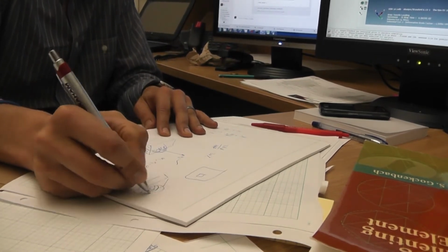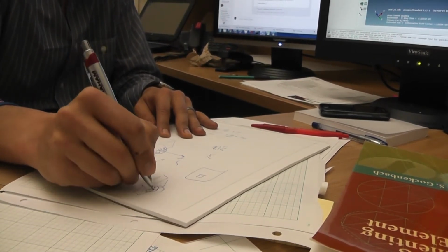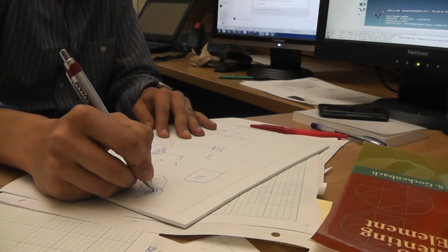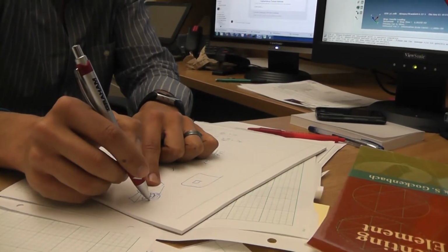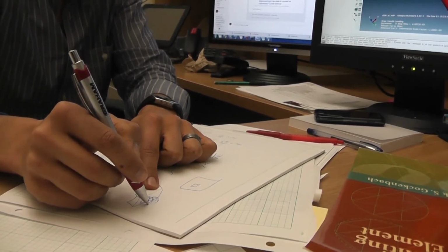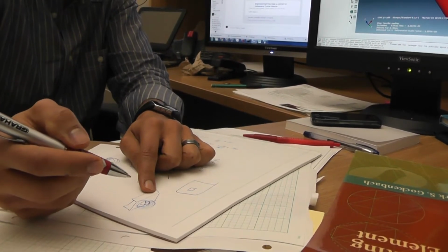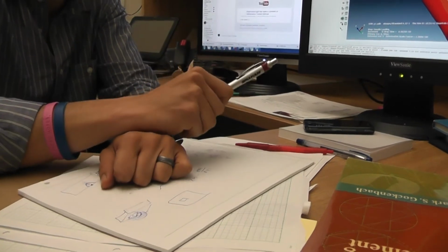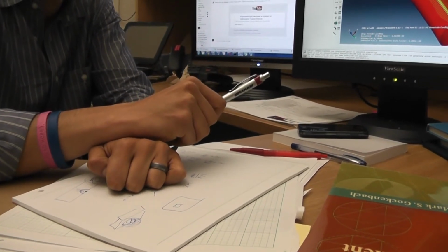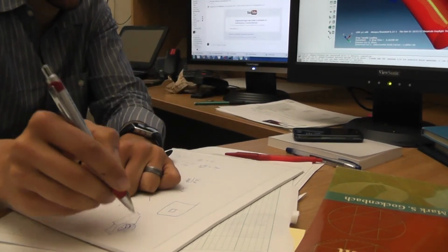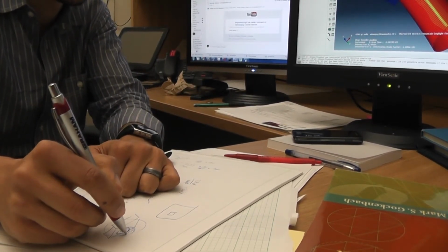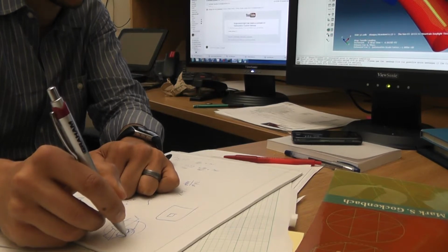Whatever handle we're going to use. You have to talk to Greg to see how this attachment will work. Before you do this, you need to know how this will work. But we don't draw the handle, right? You just can if you want. If you want to be detailed in yours, you can. But then it'll be solid elements. Like this plate would be a solid element, not shell, together with the handle. Yes.